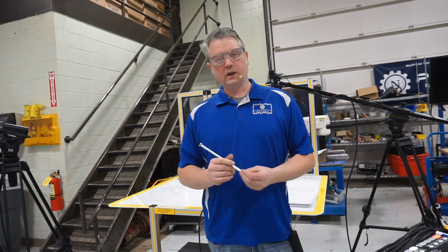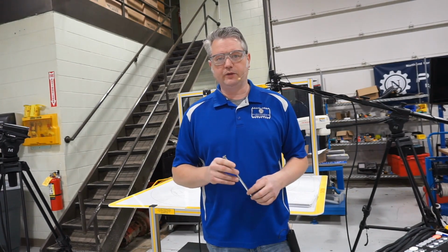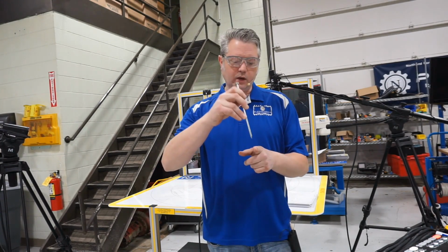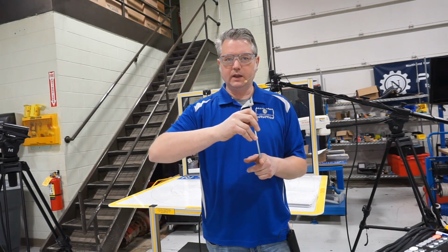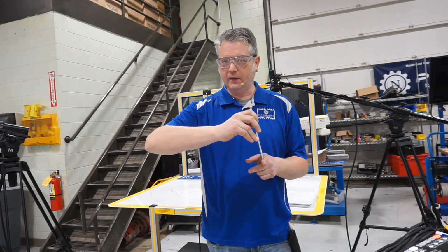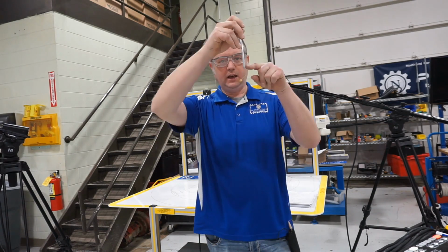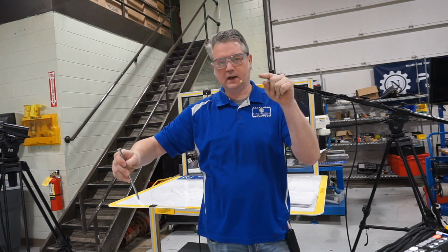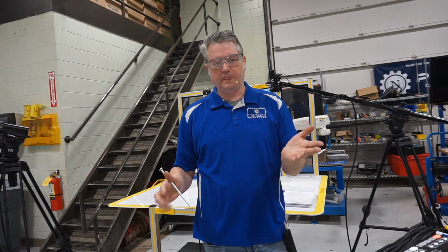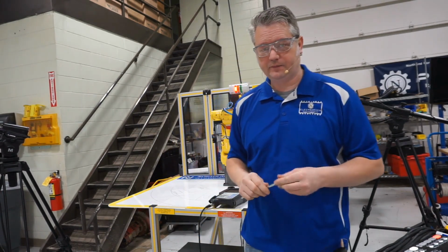The first one is called a joint move. It is the most efficient style of move for the robot to make. When we record a point and another point, the robot is going to move all joints at the same time to get there in the fastest possible manner. It may not be a straight line, and if you're going from a high point to a low point, it may take an arc as it's traveling down there, but essentially it's going to move all the axes as it needs to get from one point to the other, and not necessarily in a straight line.